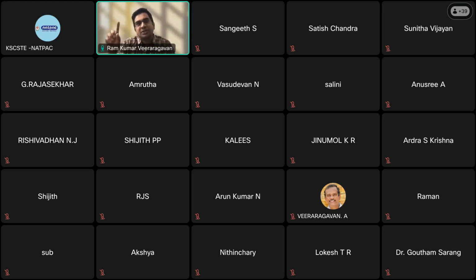But one of the things this IDEAL-RT test fails to address is the rutting potential. That's where many of the state agencies over here in the US have found the Hamburg wheel tracking test to be more representative of field performance. Out of 50 states, I would say confidently about 20 to 25 states are confident with using the Hamburg wheel tracking test. They say it's more representative of field performance in terms of moisture damage and stripping potential.